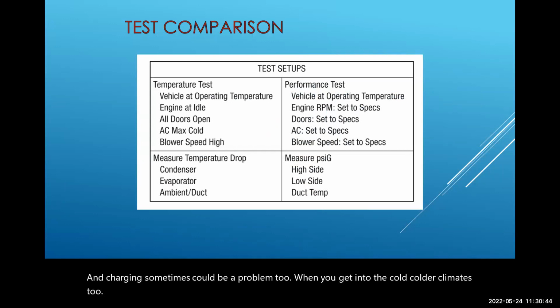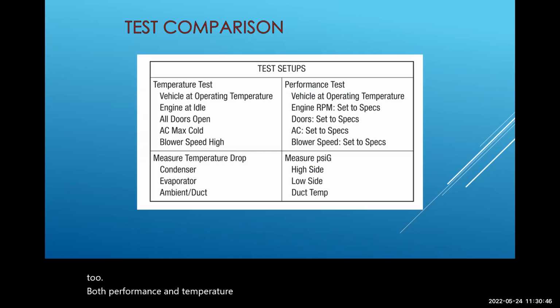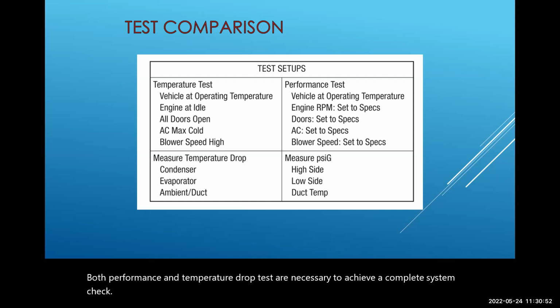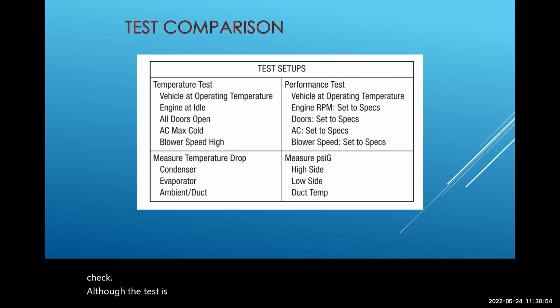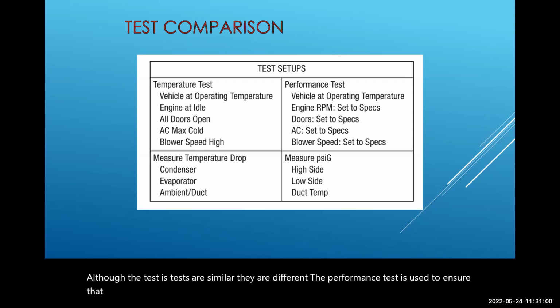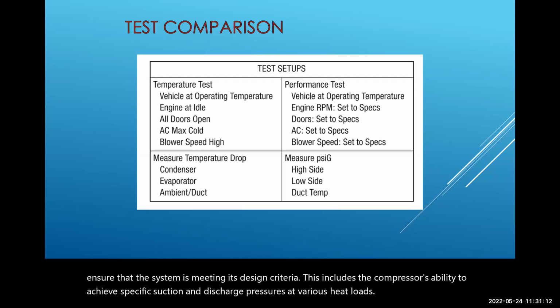Well, performance and temperature drop tests are necessary to achieve a complete system check. Although the tests are similar, they are different. The performance test is used to ensure that the system is meeting its design criteria. This includes the compressor's ability to achieve specific suction and discharge pressures at various heat load conditions.